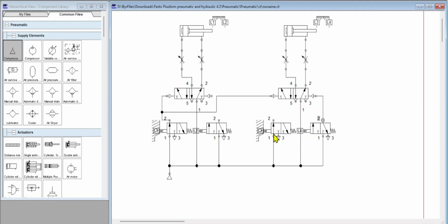Here when the cylinder 2.0 returns, pressing L3, and the cylinder 1.0 is at extended position pressing also L2, this L2 and L3 will be connected as AND. So it would be connected in series, that is equivalent of the two pressure valve.